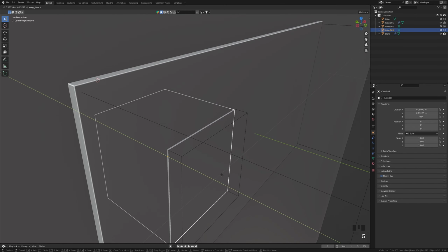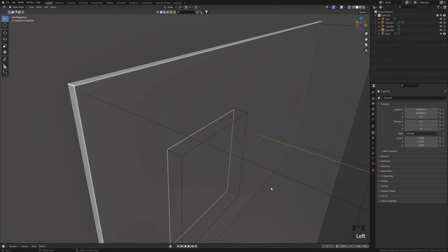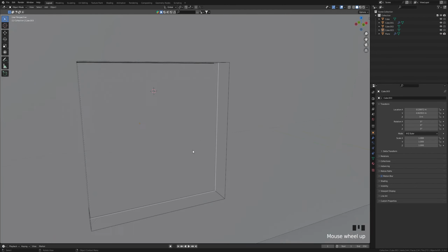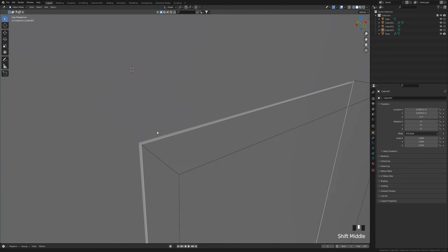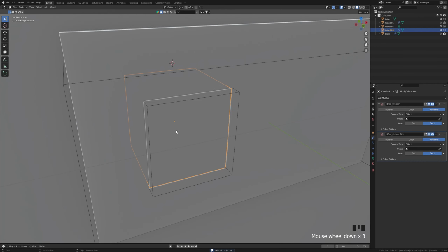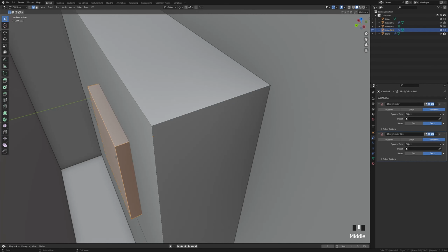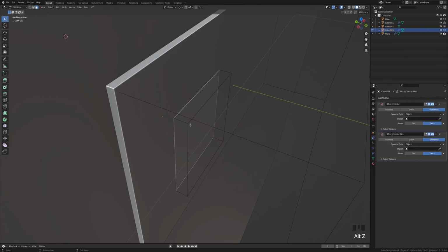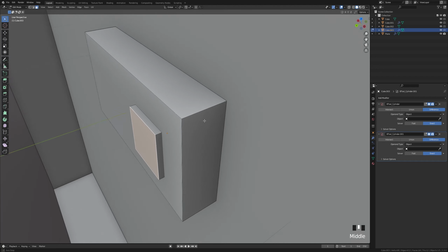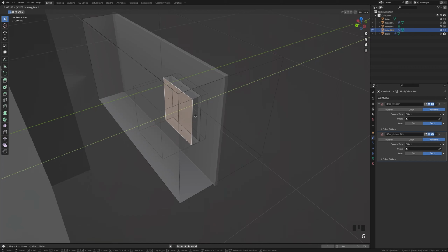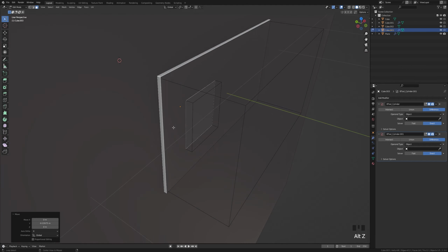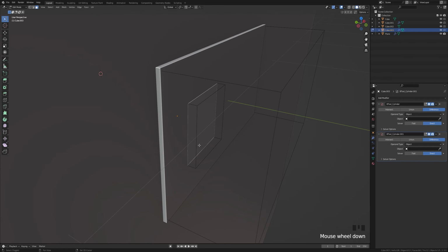You can move it inside, GY, something like this. It doesn't need to be perfect, because when you make perfect, then it slightly looks fake. So you can do slight variation like this, right? Okay. So now if you have created the shape, I can probably reduce my shape because it's like open from back. So I can go to the edit mode and GY, scale it something like this, right? Yeah. So here it is.